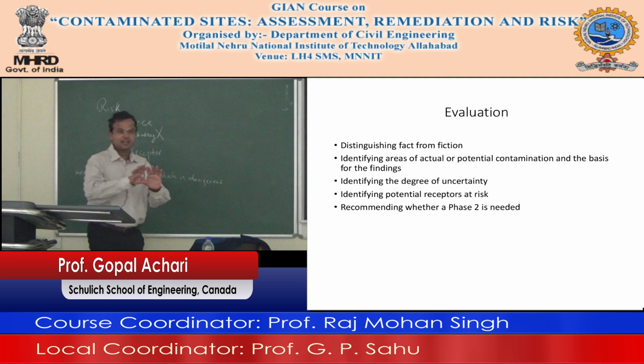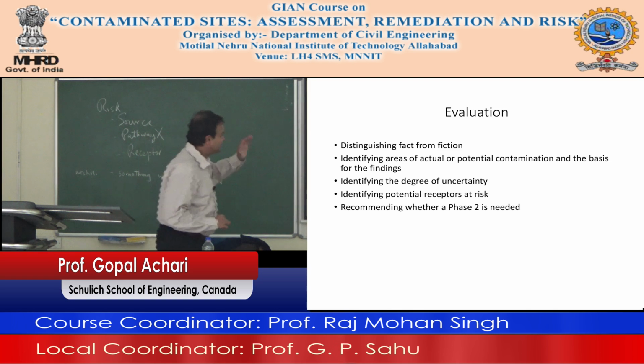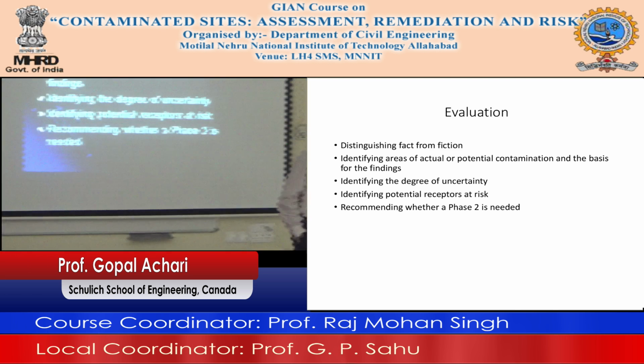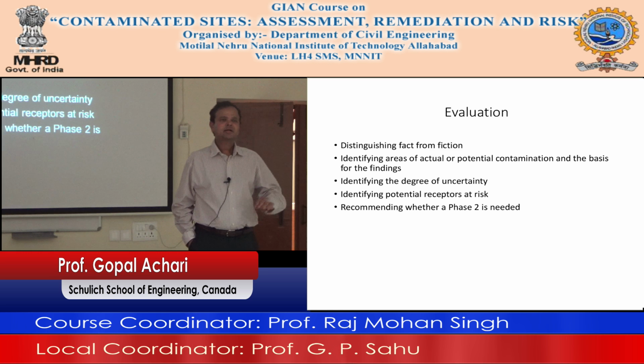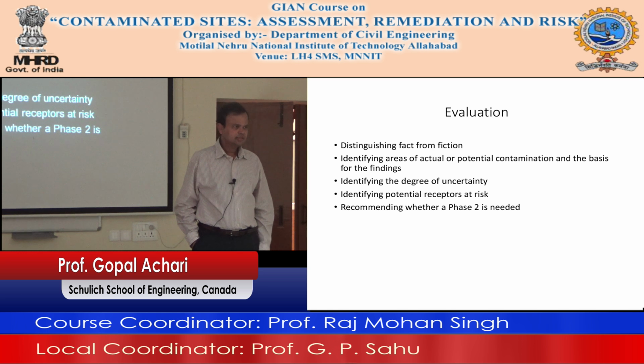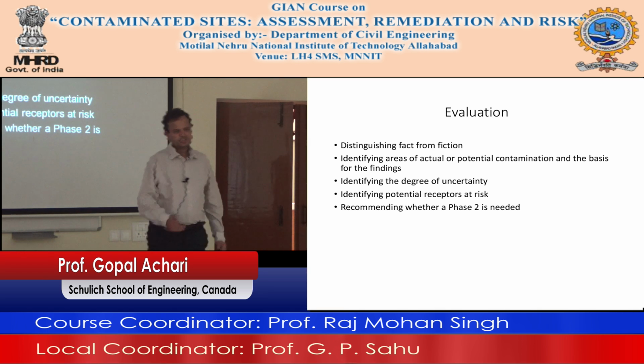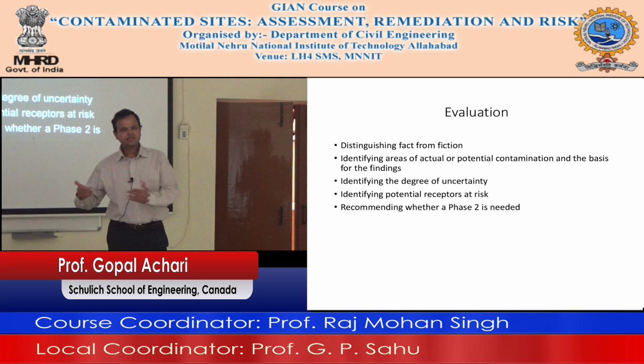Recommending whether a phase 2 is required or not: this is the key thing, and that's what the client is looking at. Your phase 1 should say, based on my entire analysis of the reconnaissance, looking at the site, the interviews, and reviewing the records, I think a phase 2 is required, and this is where you need to do it. Or, I don't think a phase 2 is required, I don't think any contaminating activity was going on here. If you say a phase 2 is required, you are expected to say what needs to be done.